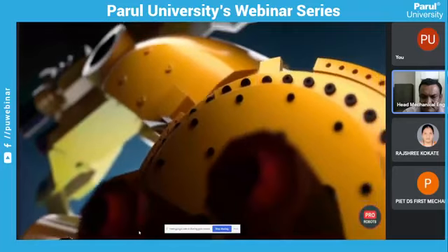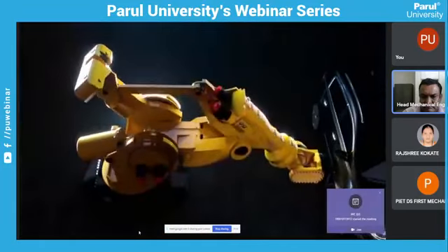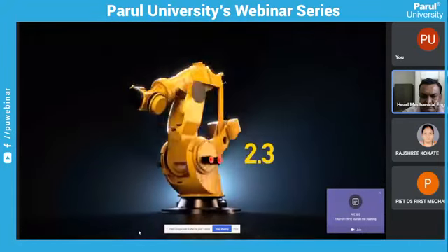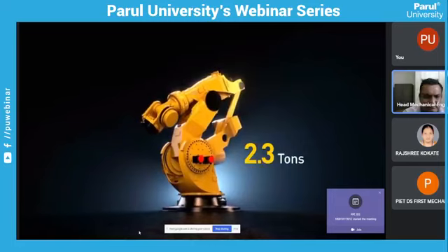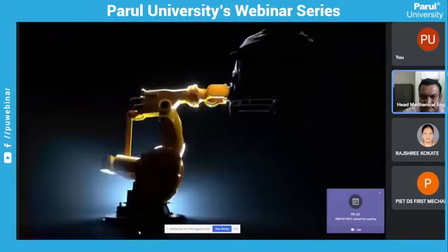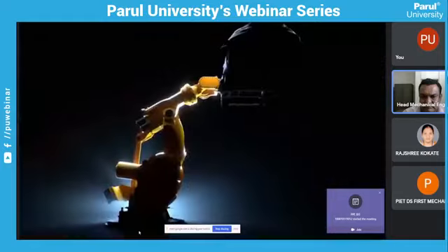Another outstanding Fanuc robot is the M2000IA-2300. It's one of the largest robots in the world. The 2300 marked with a payload of 2.3 tons. It's capable of lifting and turning very heavy objects without losing speed or accuracy to a height of almost 4 meters. The robot is also capable of lowering the lifted load to a precisely defined location.